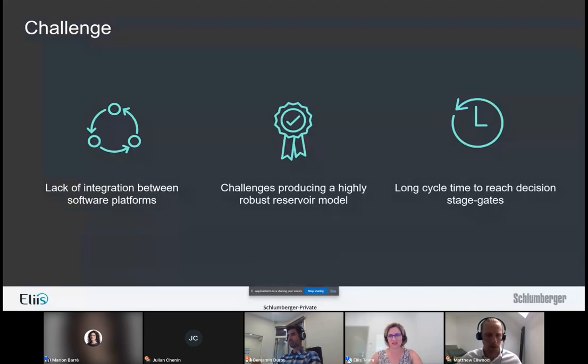Thank you very much. There is another question here. Were surfaces from the RGT model extracted automatically if they matched a well top where the surface intersects the well? Yep, exactly. That's the concept. There's a reference well, and the intersection between the well top and the RGT volume will generate a value of the RGT volume, and then we extract that iso value across the RGT volume and generate horizons based on that.